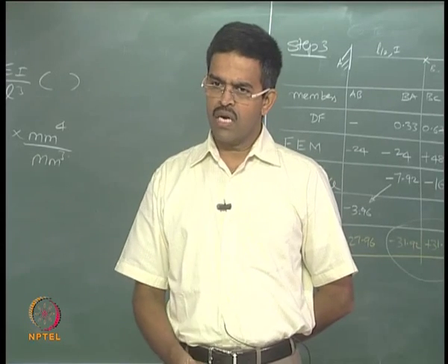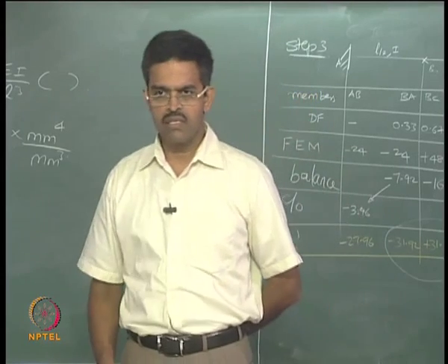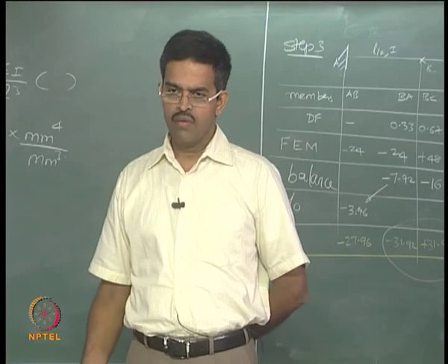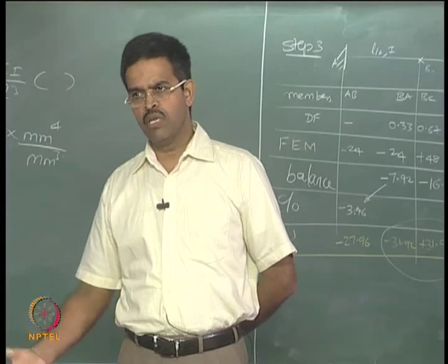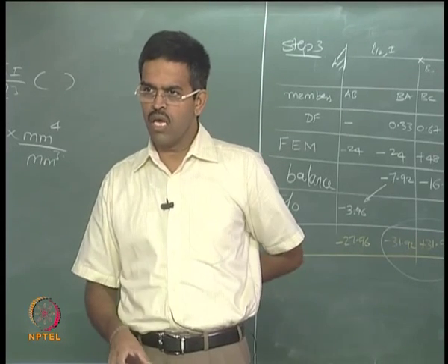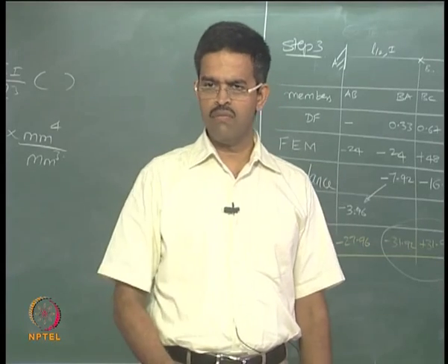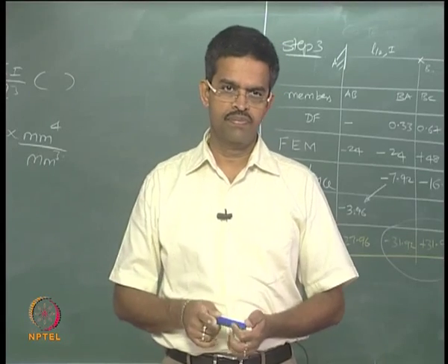The difficulty will start when you start working on the stiffness matrix and the mass matrix for a given innovative form which you wanted to derive for putting in deep waters or ultra deep waters. So, the main hitch will start only at the initial stage of the problem where you have to arrive at, or sometimes derive, the stiffness and mass matrices.